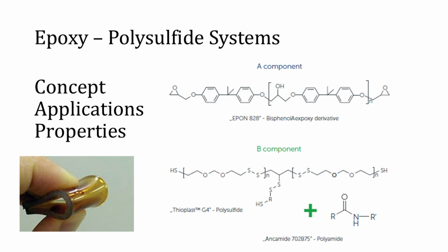Notably, liquid polysulfides have been promoted as flexibilizers for epoxy resins, with incorporation levels reaching up to 58%. While this level of addition enhances flexibility and toughness, it also influences physical strain and reduces the heat deflection temperature as measured by ASTM D648. In particular, the use of low-viscosity liquid polysulfides in fire-resistant building sealants is an important application.